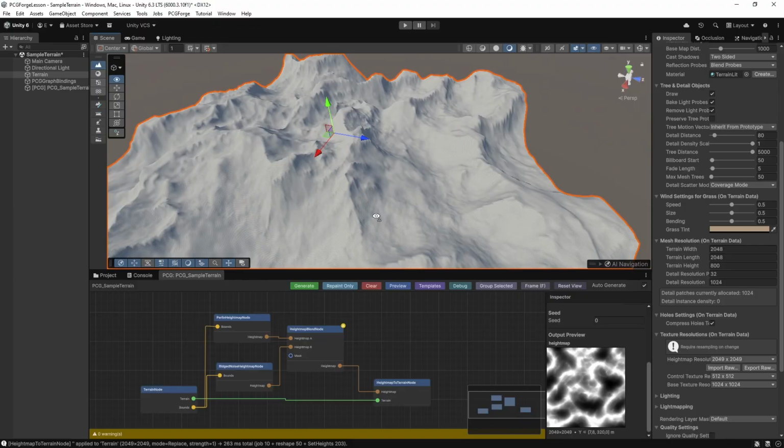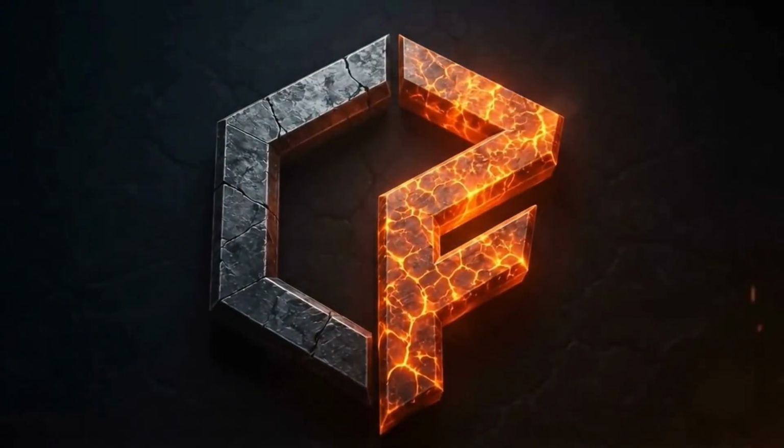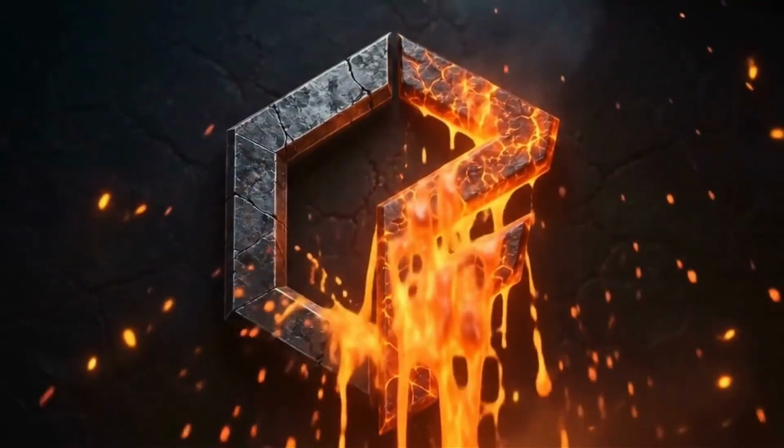In PCGForge, terrain generation follows three simple steps. First, you introduce your terrain to the graph using a terrain node. Next, you generate terrain shapes using one or more heightmap nodes. Finally, you apply the result back to the terrain using a heightmap to terrain node. You can combine and blend as many heightmap layers as you need to create more complex and realistic terrain formations.